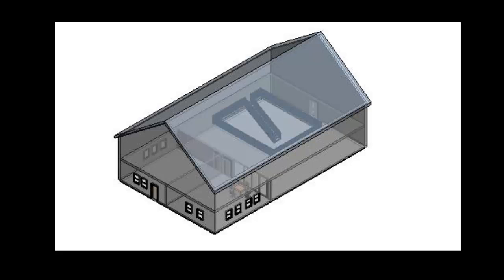In this getting started video, we'll use the architectural template and create an overall shell of the building so that next week we can pick up the site topography, some 3D solid model forms, camera view, and the rendering tools. We'll look at the basics of placing floors, walls, windows, doors, loading families, creating a small curtain wall, and stairs, handrails, and come back to those details as we progress in the semester.